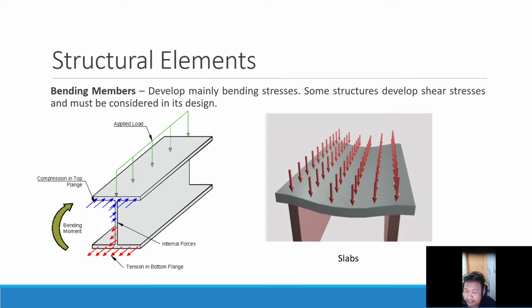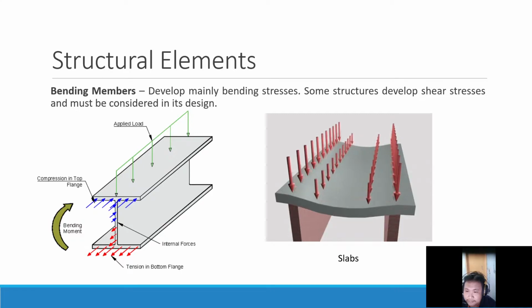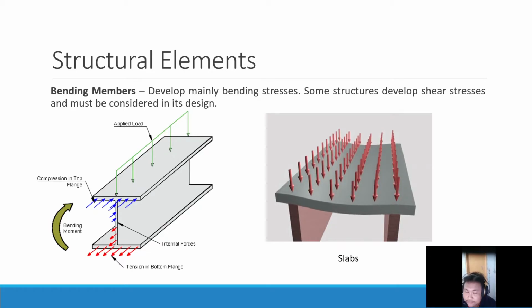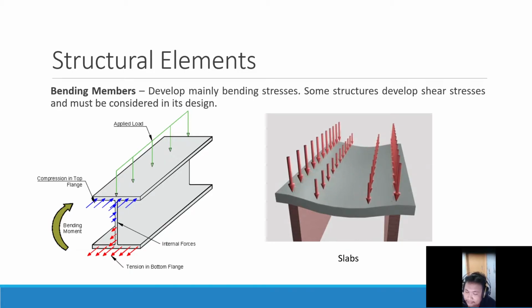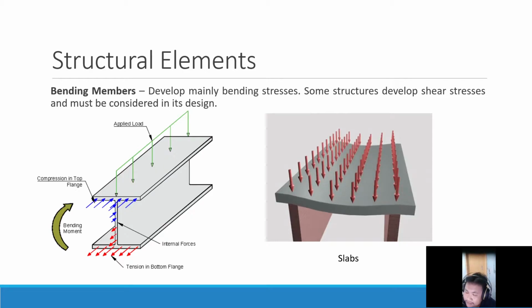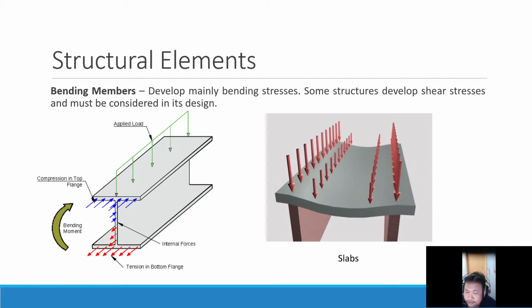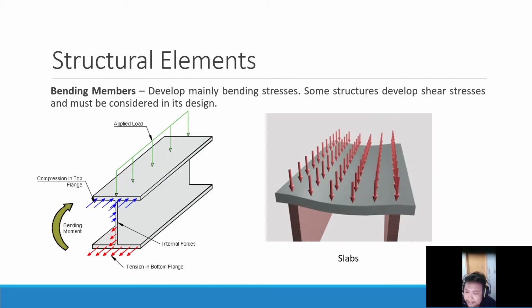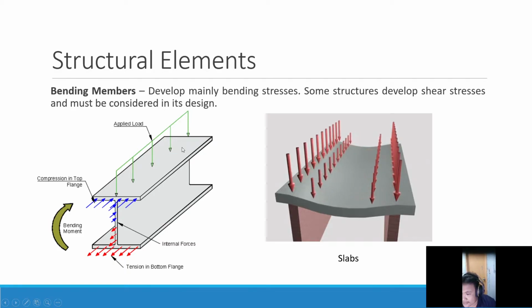Now, but mostly since it carries bending stresses, that's why when designing any reinforced concrete, we mostly design for its longitudinal reinforcements because those reinforcements will counteract the effects of the bending. Now, mainly in reinforced concrete, the reinforcing steel is placed at the bottom to counteract the tension, if this is our beam, if the load is here. But anyways, let's move on.